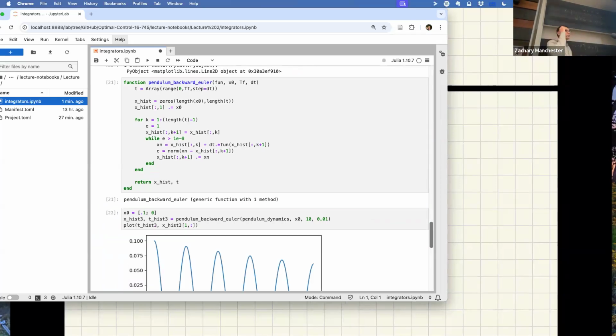It always undershoots and you get artificial damping. Backward Euler is one of the standard methods used in robot simulators. It's what's used by default in MuJoCo, Bullet, probably Isaac, although I don't know for sure. All these stock simulators use backward Euler. Why? Basically, this artificial damping is desirable because it means the simulator won't blow up and do stupid looking unphysical things, but it's still wrong. So keep that in mind. Pretty much all the sims you're running, like MuJoCo, etc., actually have artificial damping added to the simulator to make it such that really unphysical blow up stuff doesn't happen.